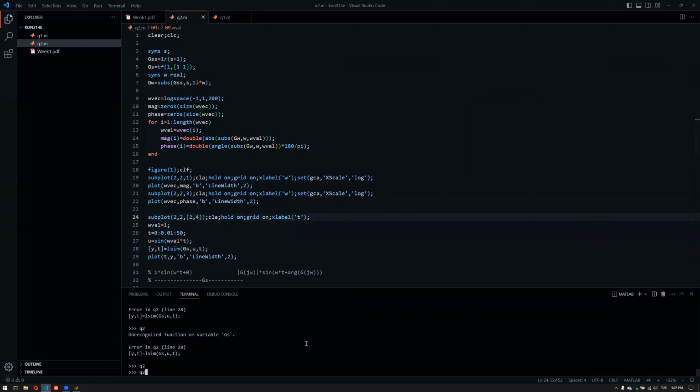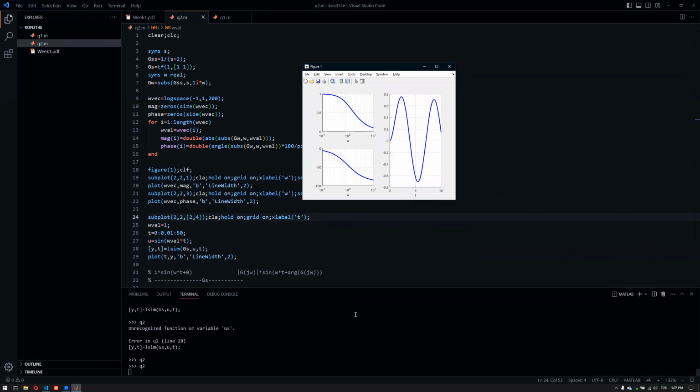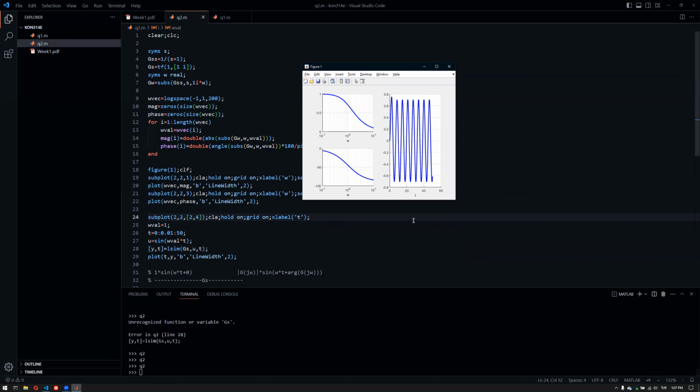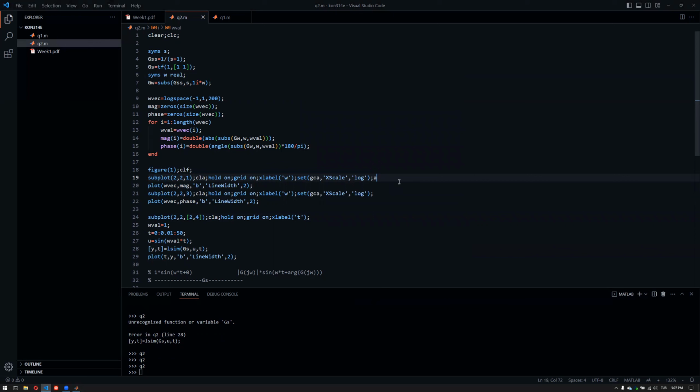We have grid on, okay. There we go. Now I want to save this subplot to AX1, and the way you can do that is basically AX1 equals GCA, where we also use GCA here for set and get. This is not going to be that important for the upcoming lessons, so you can just copy and paste it and never think about it. Here we use AX2. GCA stands for get current axis, by the way.